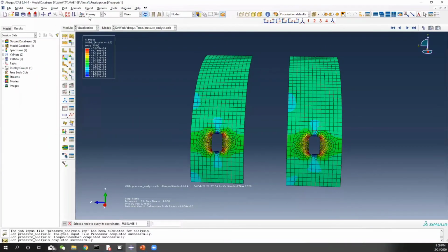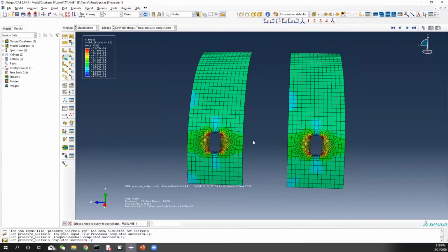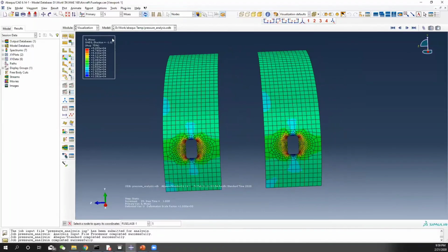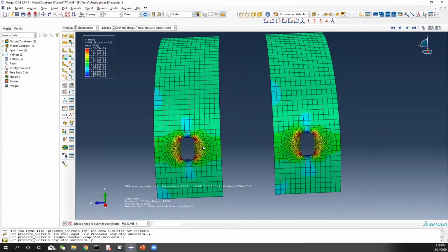Now we can compare the stresses and go back to your material property to check the strain. The ones related to your plastic stress and strain are the von Mises stress and the plastic strain.